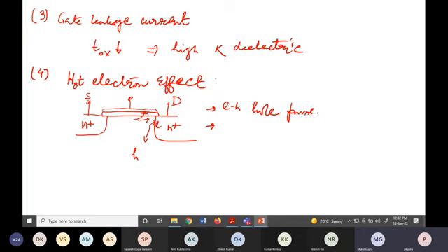You remember we discussed we can't reduce the threshold, the supply voltage that much, because that will affect the analog designer to design the circuit. We can't reduce the supply voltage that aggressively, like alpha times. So that is why the generalized field scaling came into picture. So the electric field from the gate side is also quite large, because we fail to reduce VGS that aggressively. So that might take the electrons in the channel to penetrate through the gate oxide.